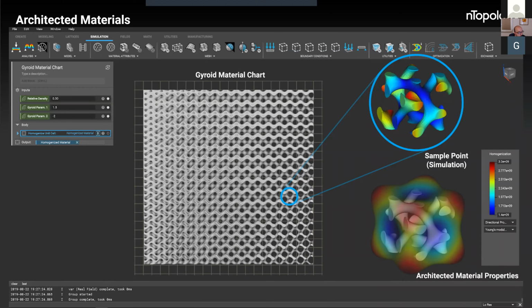And can we do multi-material topology optimization for lattice structures? For instance, if two materials are defined simultaneously to optimize the geometry. So we don't have the ability to do topology optimization right now with multiple materials. It's an area I'm actually really interested in. But you could actually set up this geometry to have multiple materials in it. If we think about implicit geometry, one of the benefits of this modeling approach is that things like Booleans, whether it's subtract or union, are really easy. So you could actually subtract in or union in with different objects to represent different materials throughout the structure, and then directly slice that. So you're not trying to mesh with the interface mesh or anything like that. It's just directly slice that geometry and send it to your printer.